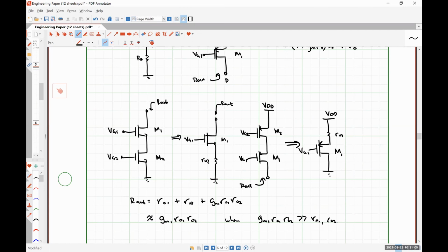We have an infinite input impedance at very low frequencies, which means our gain can go up and up and up. For the BJT, we are limited by having a finite input impedance of rπ. That's what keeps it clamped down to a couple of hundred kilohms to megaohms or whatever, depending on what our Early voltage is. This guy, sky's the limit.